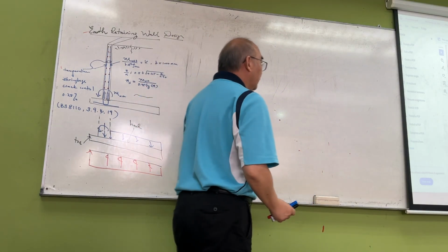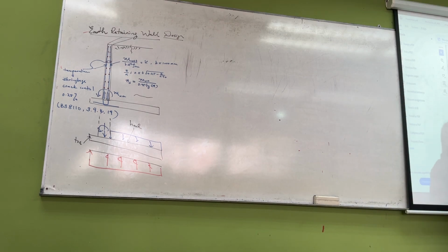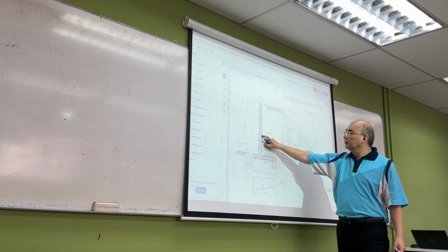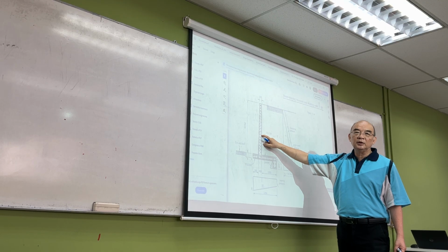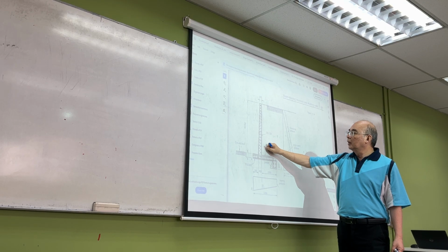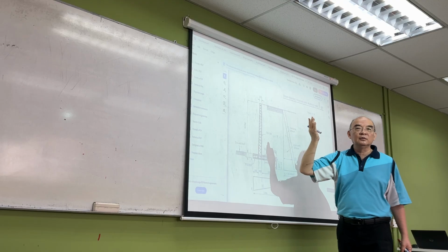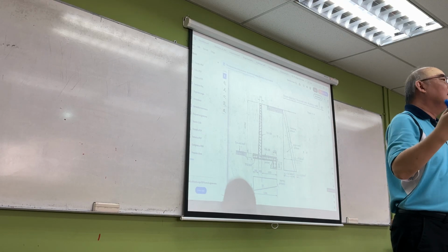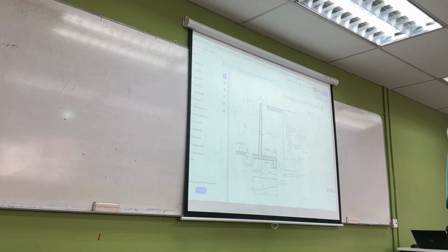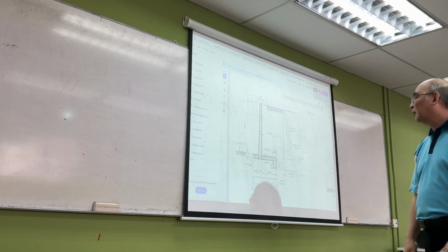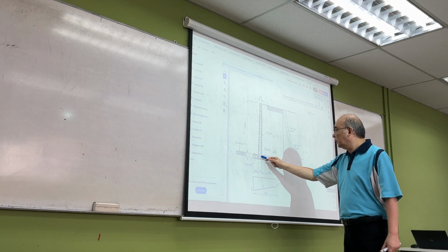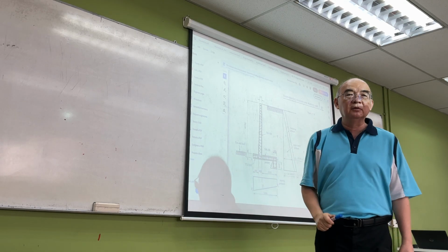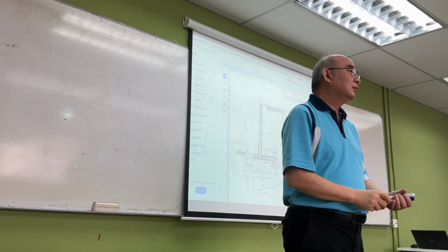So when you look at this design, here they say T20 at 200. Looking at this one, T20 at 200. But the rest they didn't give you. They show it to you, saying that we will have rebar there, but they didn't tell you how much to put in. Same thing here. In other words, they only design for the structural reinforcement.